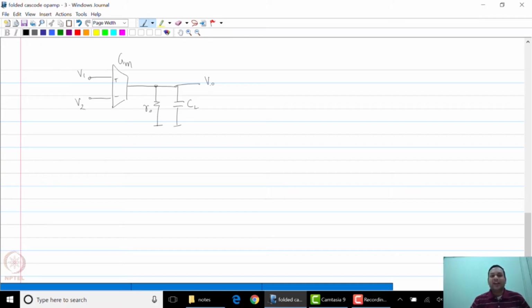you are basically trying to create, you started from a one-stage op-amp which had a simple transconductor. You went to the telescopic op-amp which looked like a better transconductor. And now you have a folded cascode which still looks like a very good transconductor, much better than the regular original one-stage op-amp because R out is large. But the swing limits are expected to be better than that of a telescopic op-amp.